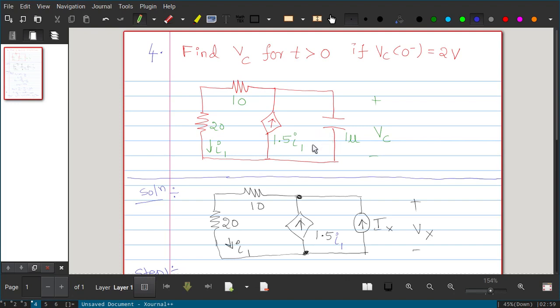For that, you have to find R equivalent like this. This is similar to how you find it in analog electronic circuits. In a given transistor or any amplifier, you are asked to find the input resistance, the output equivalent resistance. How will you calculate there? You simply add a test voltage source or current source, and find the ratio Vx by Ix. What you get is nothing but the equivalent resistance. So the same principle we are going to use here.